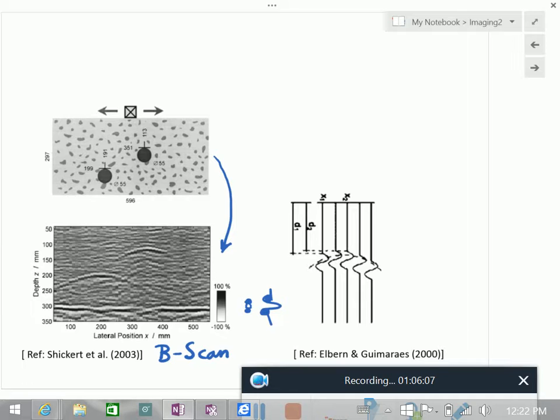But it's good that now we came back to this figure. Pay attention that where we have the hole, the reflections of the back wall also are kind of distorted. This is another way that sometimes people, especially if this hole was in the near field of my transducer, maybe I would not see a nice reflection like that because of all the stuff we talked about.